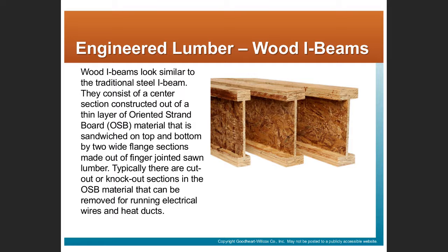Yes, I think these wooden I-beams would be used typically for floor joists or ceiling. Again, we're looking to span a longer dimension. So as we have a longer span, we either have to have them spaced closer together or have bigger members, right? 2x8s or 2x10s or 2x12s.